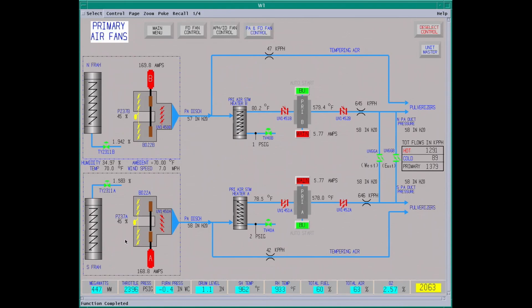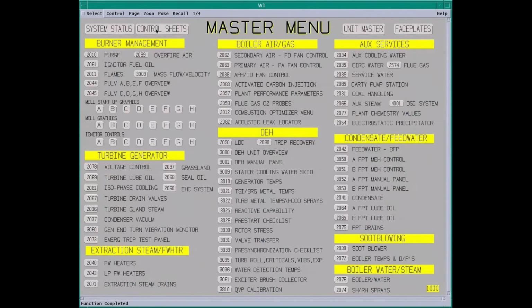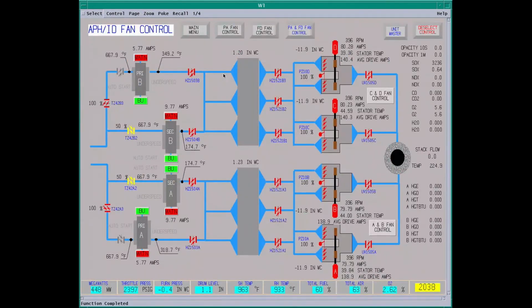Primary air fan screen again. Dampers at 45, still 58 inches. 578 degrees coming out. A little bit more heat coming through. We will have to adjust. We have the dampers feeding the various air preheaters. They're 100% open on the primaries. Secondaries are still pinched back a little bit. We'll let this temperature go up more. If it gets too hot, it can cause problems in your precipitator.